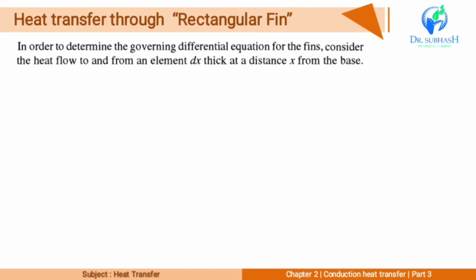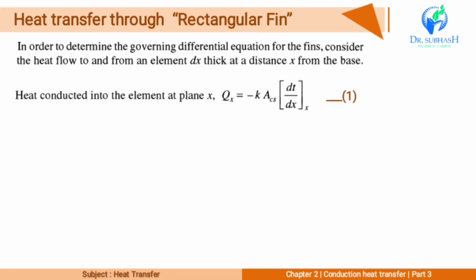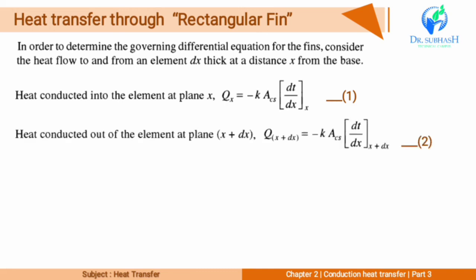In order to determine the governing differential equation for the fins, consider the heat flow to and from an element dx thick at the distance x from the base. Heat conducted into the element at plane x, Qx, is equal to, from Fourier's law, minus kA dT by dx at x. That is equation number 1.